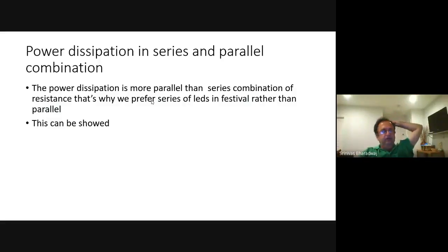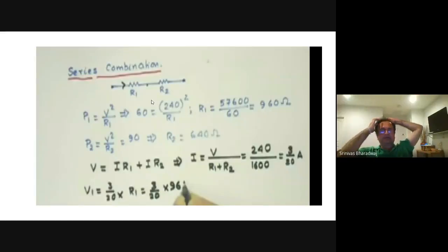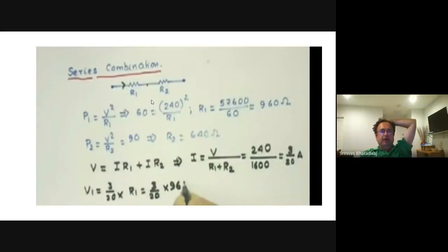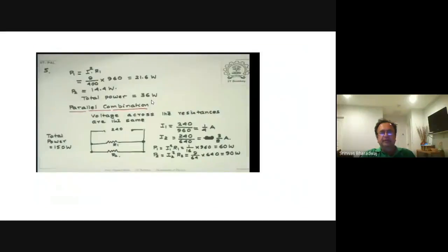So intuitively, when you connect circuits in parallel, it's supplying the full voltage to both the elements. Otherwise, they share the voltage. Okay, so V square by R is the power. So here he is calculating two resistors in parallel and two resistances in series, and then he is looking at which consumes more power. Okay, and he is saying that the power is greater in the case of the parallel combination.